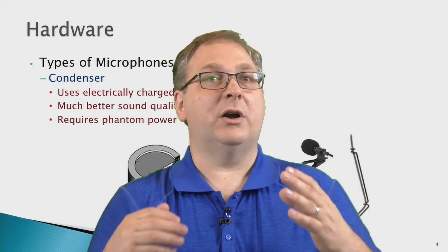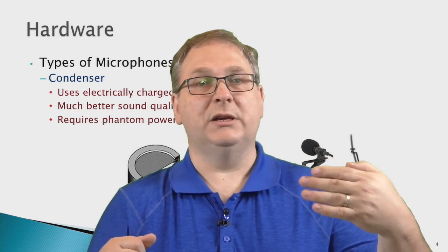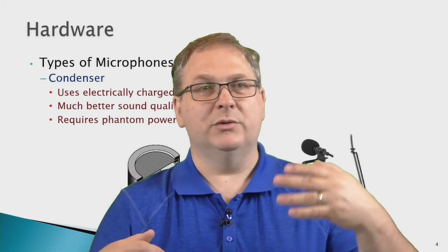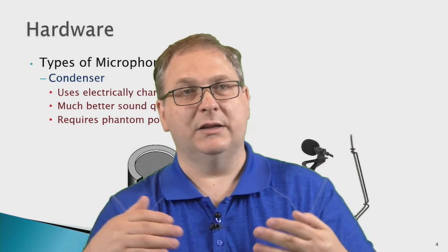That being said, there are other differences between the microphones, such as a dynamic mic generally can take more volume, more sound pressure into the microphone without distortion, whereas a condenser microphone oftentimes does not have enough capability to take high levels and might distort. And so you might have reasons why you want to use a dynamic microphone versus a condenser. So those are things to think about.